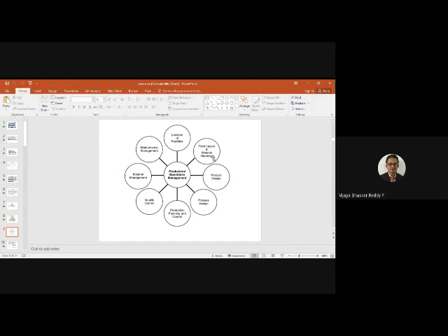First pick up the raw material from the stores and load it in the machine. First start the facing operation, then the turning operation. Turning also may not be possible in one stage, maybe two or three stages. Then the threading operation, knurling operation, then cutting, the parting operation. Like that, different processes will be carried out.